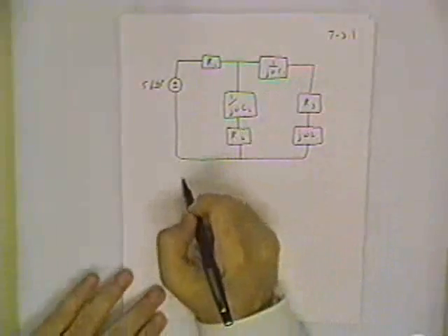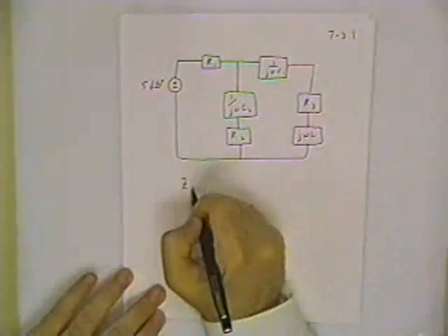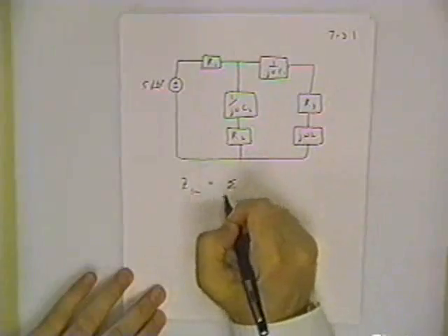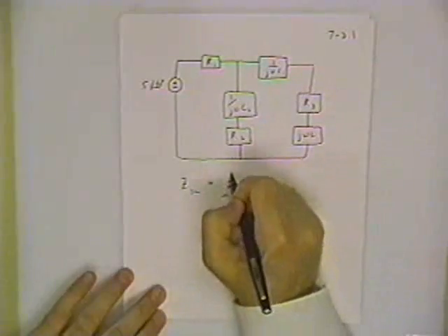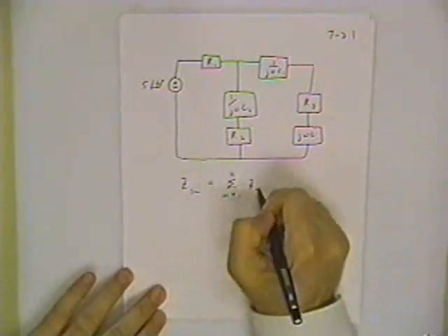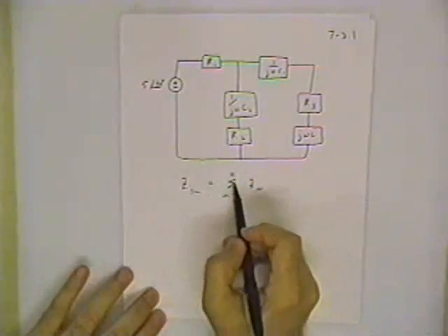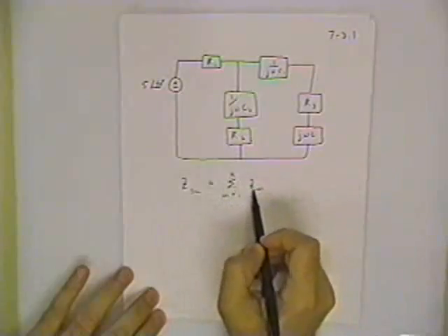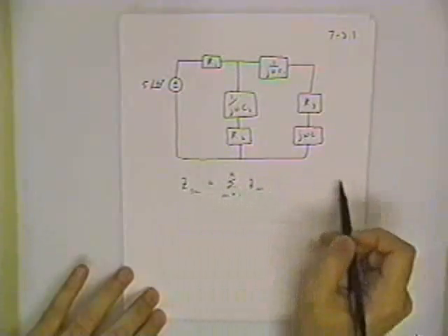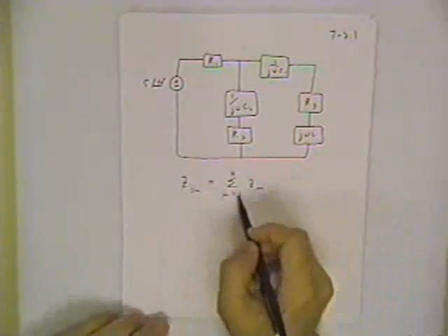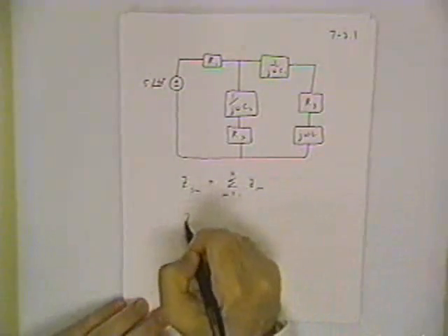And that's a key concept, is that in series connected impedances you have the same sum rule we had for series connected resistors. If you have capital N impedances all in series, you just add them up algebraically, remembering to group the real and imaginary parts. You come up with a complex number equivalent here.